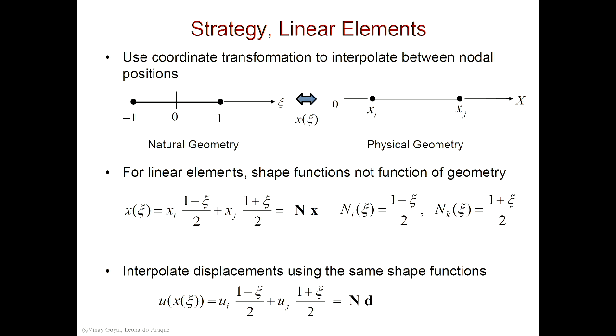To do that, why not use the shape functions that I have previously defined as the ones that are going to help me do this mapping? I'll just use these same guys that I had defined in this coordinate system. Let's see, for example, if these shape functions actually work out. If I use this shape function for that node and this shape function for this node, let's see if this actually makes sense. So ξ at 1, do I get 0?